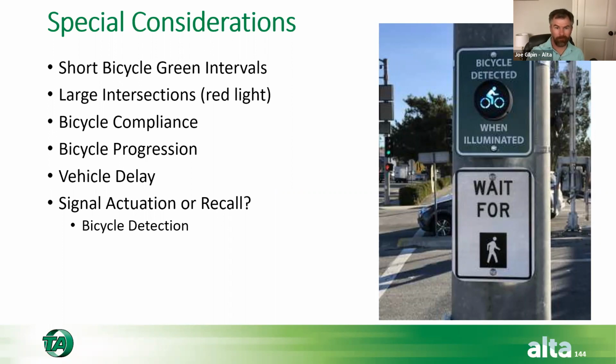There's like a 3-second fixed time for that. So then the bicycle signal goes red and you haven't even gotten halfway across the intersection yet. And you're seeing, from a bicyclist perspective, red light all the way as you're going. Now the signal is probably timed to allow you to do that, and there's going to be all red for the cars too that supports that. But it's uncomfortable for bicyclists at really large intersections because of that short yellow interval that gets built into it.